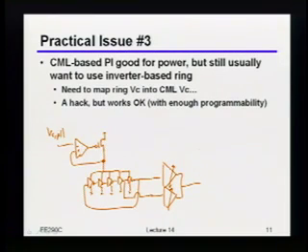But remember, I really need to control the slew rate of those phase interpolators, right? So now I again need something that tells me what is the actual frequency that you're using? Well, just like before, the most convenient thing to use is still that PLL control voltage. Now, the only piece of bad news is that PLL control voltage really is not looking at the same structure as the phase interpolator is.